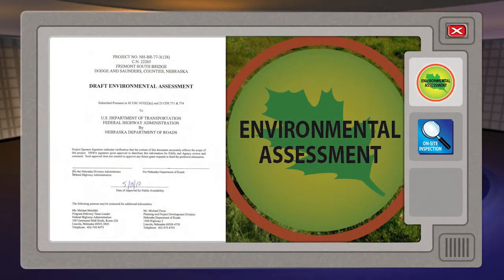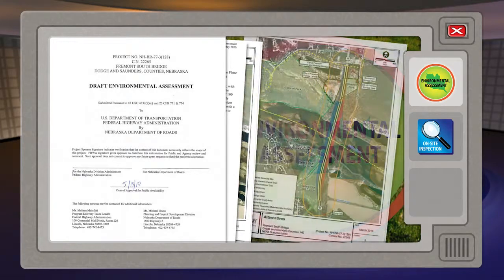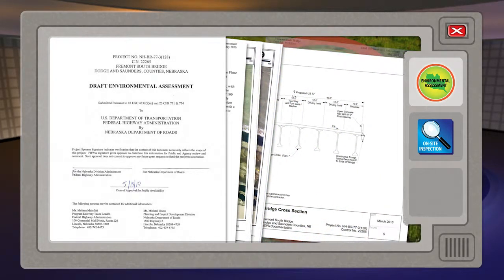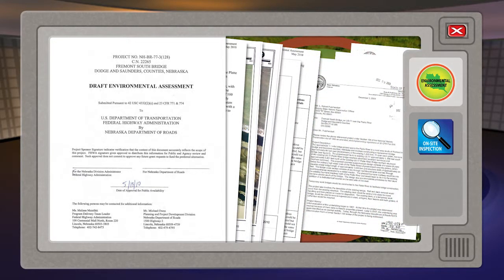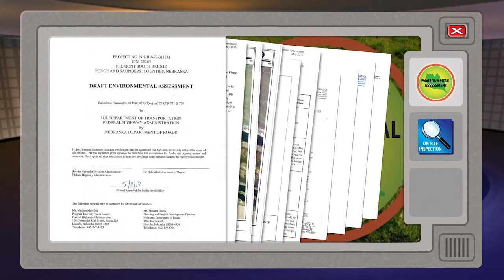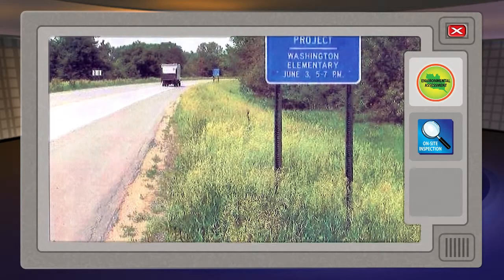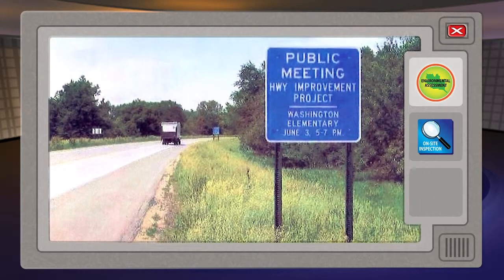The environmental assessment includes the project scope, preliminary design, description of alternatives, review of the topography and cross-section surveys, discussion of the impacts found in the field inspection, and a listing of agencies and persons consulted with on the project. For large capital improvement projects, this information is compiled and presented at a local public hearing to present the project to the community.